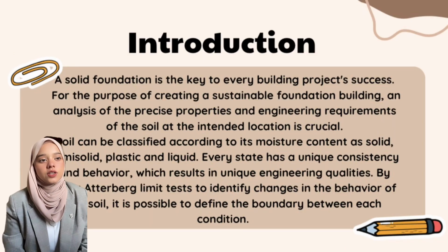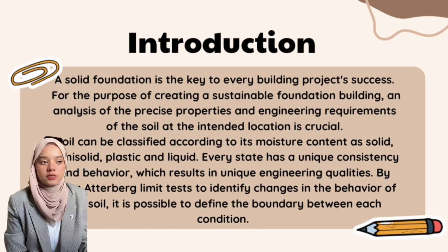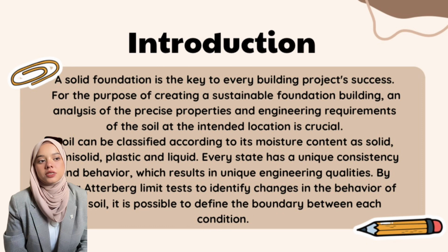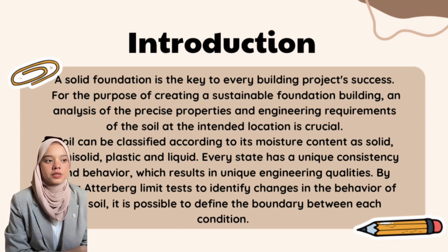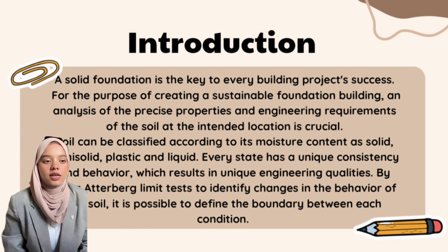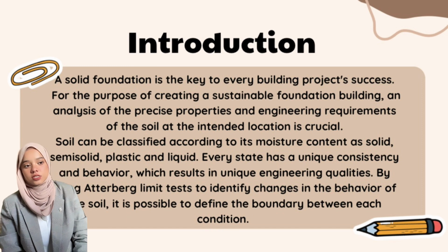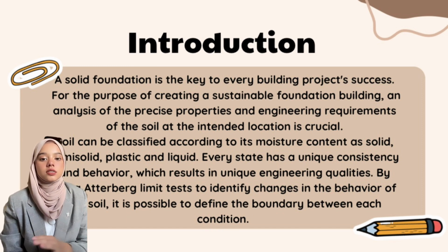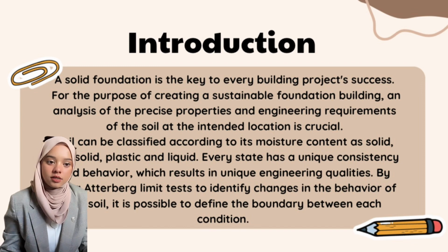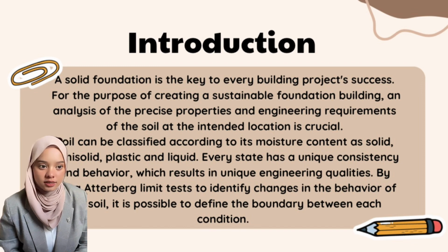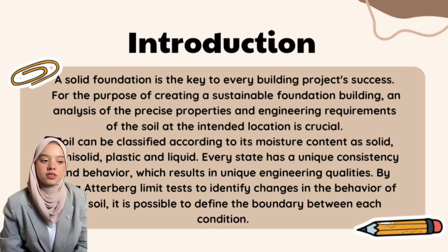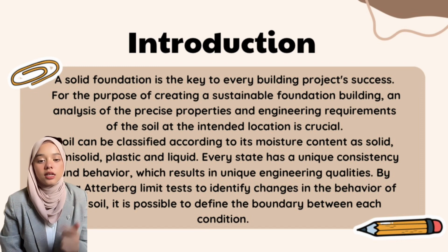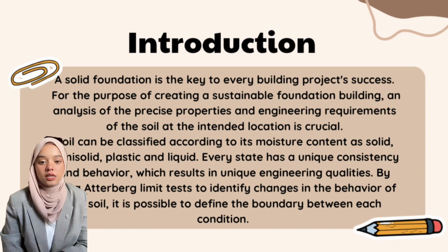So, a solid foundation is the key to every building project's success. For the purpose of creating a sustainable foundation building, an analysis of the precise properties and engineering requirements at the intended location is crucial. So, in this individual mini project, students are required to conduct certain soil engineering tests that can be associated with soil mechanics fundamental concepts and describe the soil in terms of the particle density, liquid limit of soils, and plastic limit of soil.